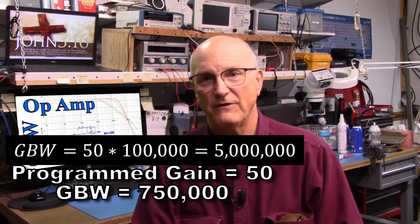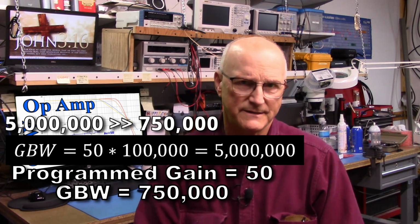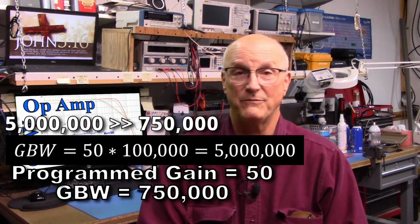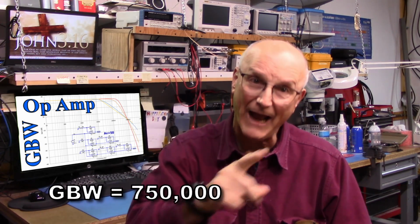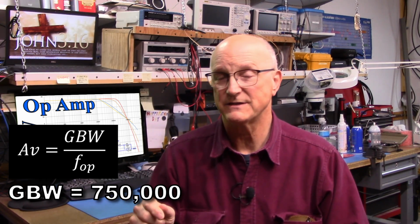100,000 times 50 is 5 million, and this does exceed the 750,000 number from the gain bandwidth product of the op-amp. So now what? Now we employ the gain bandwidth product, which is 750,000. The gain of our amplifier is now the gain bandwidth product divided by the operating frequency.